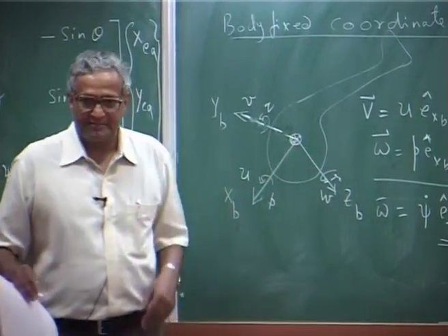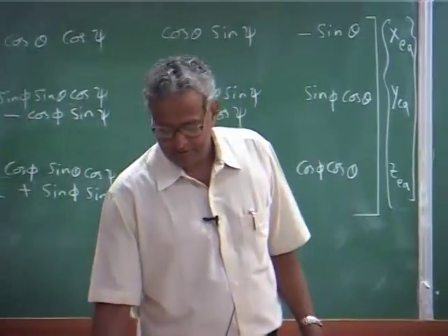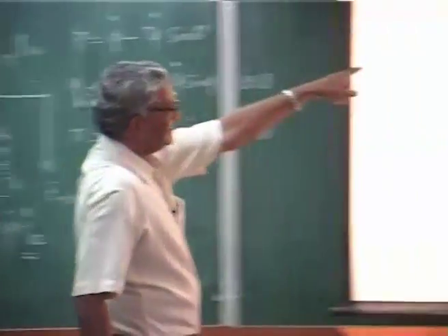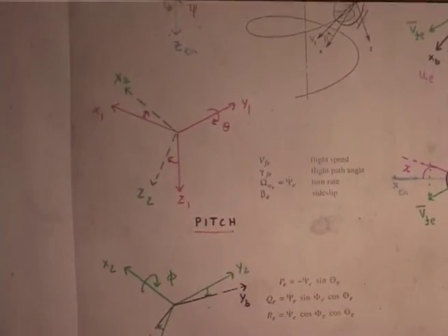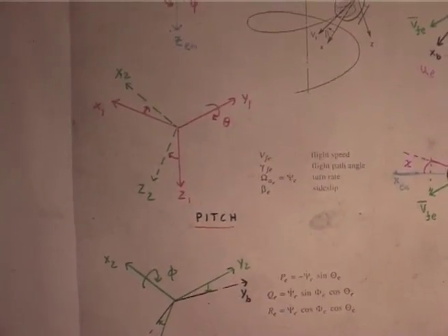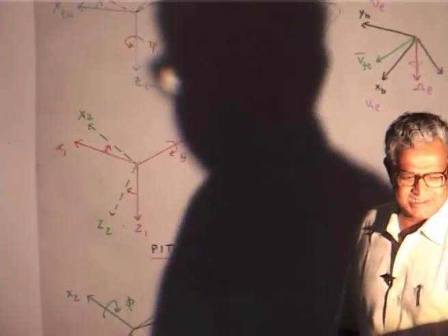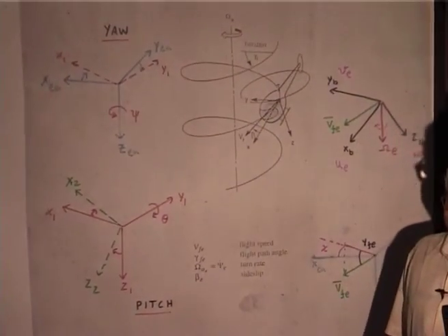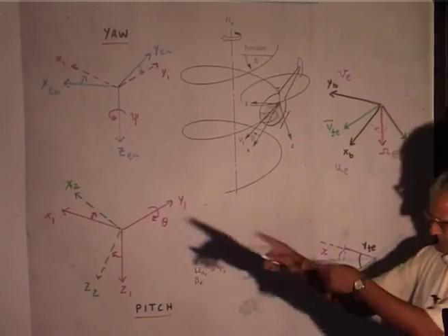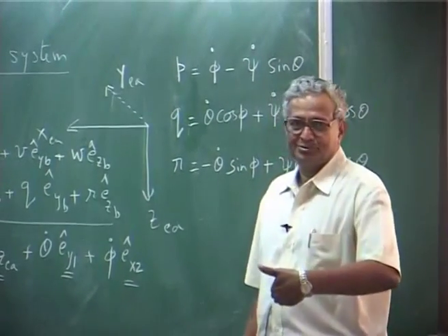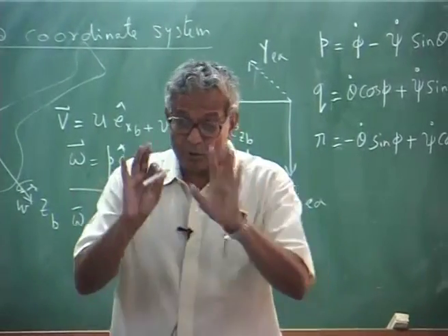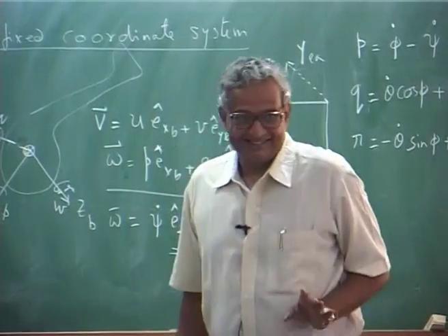Now, if I want, yeah. Again, like the theta, phi and psi. Yes. Now they are with respect to what point? As you have defined here. Okay. That is why the sequence you follow is the most important thing. This is the sequence we are following. Suppose if you change the sequence, you will find a different thing. That is why I said usually the yaw, pitch, roll sequence is followed, so that everybody understands the convention, and the coordinate system also they try to use the same thing. Okay.